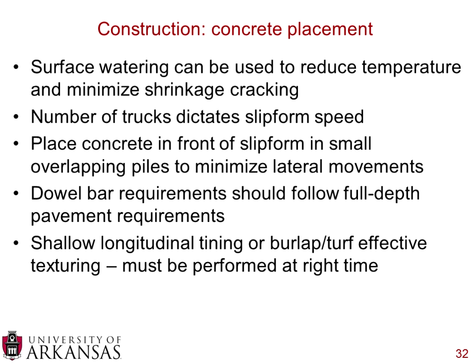So when you're doing your analysis and you determine that optimal steel depth, it'd be the same as doing a traditional pavement. That's where you place the dowels. Once the concrete has been placed, they recommend either using longitudinal tining or burlap or turf dragging over the surface so you get some effective texturing.